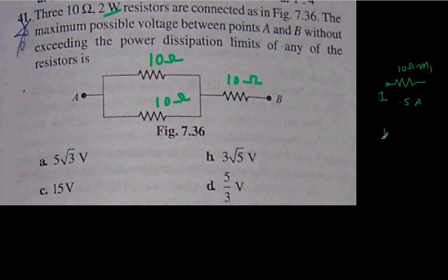Because I square R is the heat which will generate over here, and if this material does not have the capability to sustain 0.5 square into 10 joule energy, then this will get burned out. If you change your material, M1 to M2, this current may change, it may sustain more current, it may sustain less current.